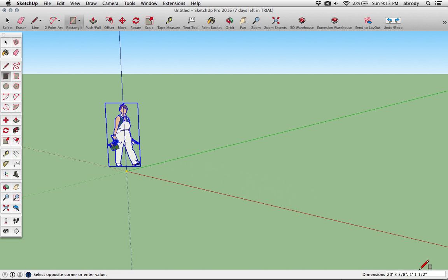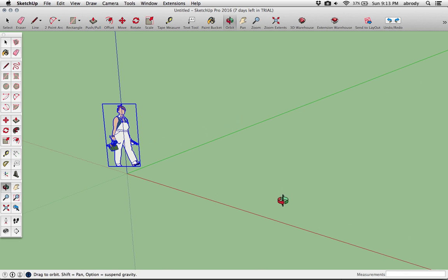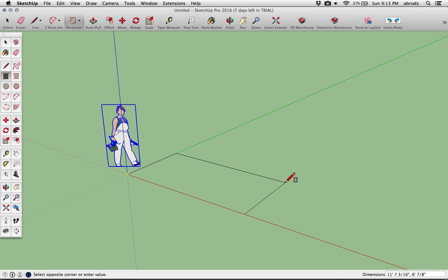Anyway, when you draw an object in SketchUp, you see how it tells you your dimensions down on the lower right. Well, rectangles are funny in that there's two dimensions, a width and a height. And when I click to draw my rectangle, it tells me how big it was. But like with a lot of commands in SketchUp, you can change that number. And I'm just going to change this by typing, 8 feet, comma, say 30. And I don't even have to type in the little inches sign. Everything is in inches. When I hit enter, you see how it resizes the rectangle.